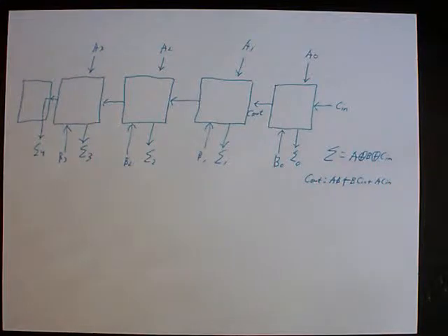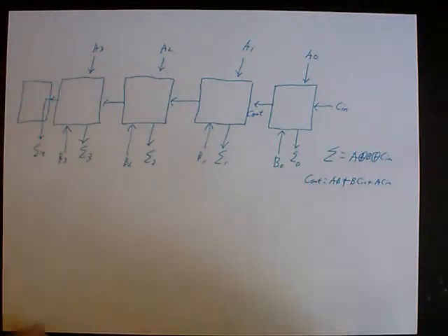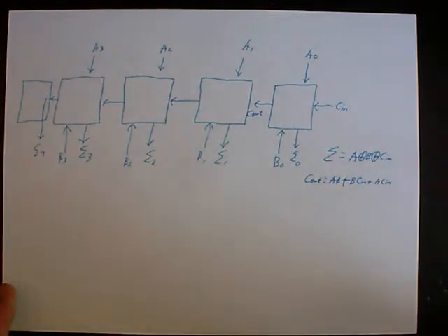And again, this is just standard digital logic. There's nothing cell matrixy per se about doing this. This is exactly how you would design a ripple carry adder using 4 full adders. And in this case, a full adder happens to fit in one cell. So the tiling is quite natural because of the way the outputs feed from one cell to the inputs of the next. So we can lay this out.